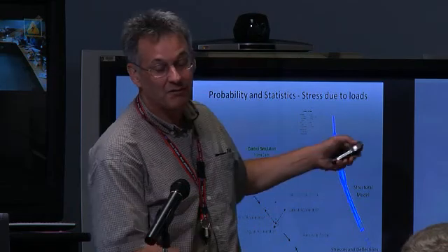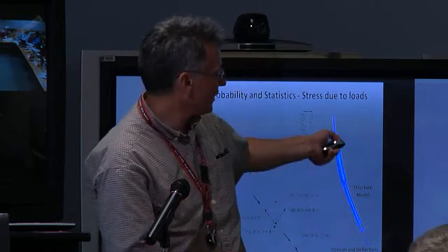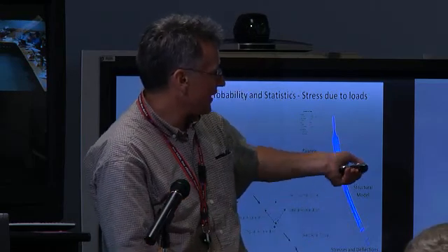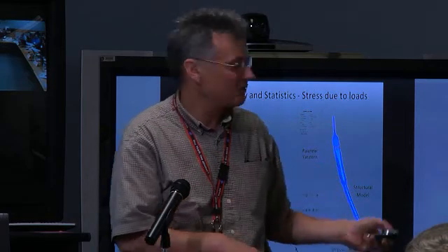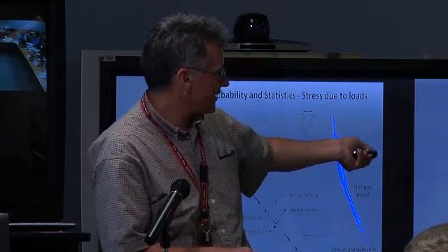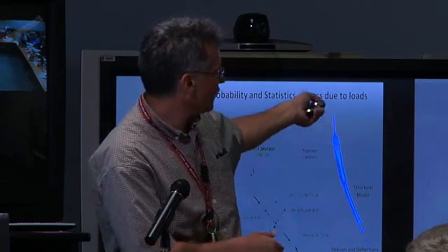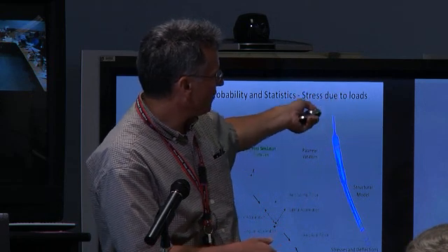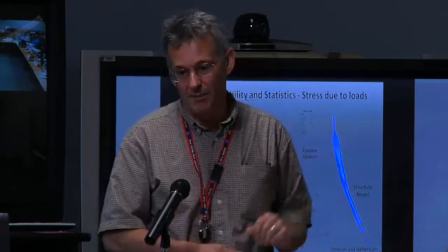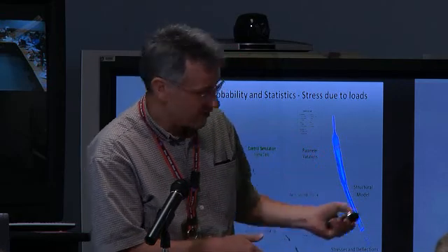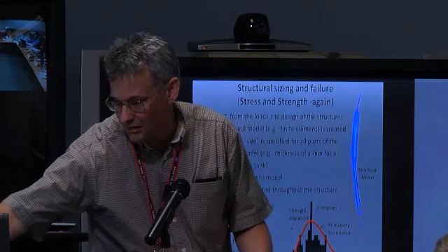But we do take that, and it goes into a flexible model. So now all the dynamic models of the structure, which can vary and have bending and things like that, can give you loads. Based on that, we get all the stresses and deflections of a structural model. For every instance of that Monte Carlo simulation, we get one result that shows you all the bending, deflections and stresses in that model. And we run another simulation that goes into Monte Carlo, another single wind profile choice, one choice of parameters, and rerun that analysis. You essentially go through this process of Monte Carlo, just a formal way of going through all these parameter variations in order to get some statistics on your outputs, which in this case are stresses and deflections. So that's our loads. We care about the stresses due to the loads.